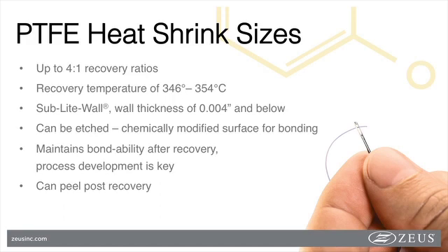So let's extrapolate all of the properties of polytetrafluoroethylene to the PTFE heat shrink. This heat shrink has valuable mechanical properties because of the material's stability at elevated and low temperatures. It has exceptional chemical resistance and good dielectric strength. It can be sterilized using more than one method.